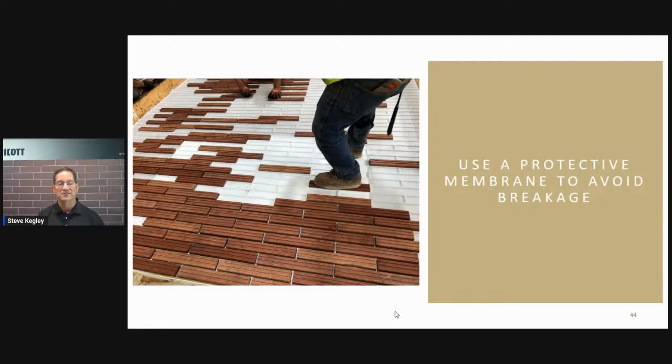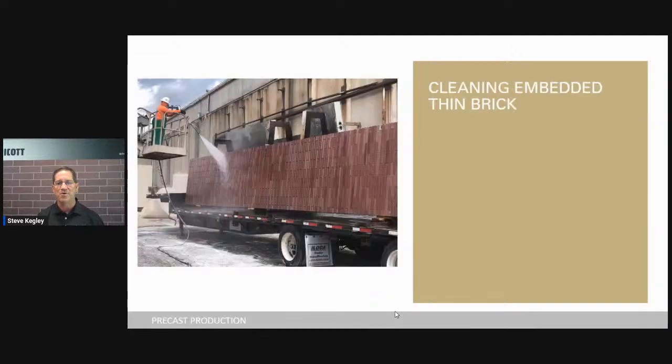Great practice to prevent that, because what's going to happen is he may slightly crack that, not know it, not see it, not take it out and replace it. Concrete gets poured in there. Now you've got to dig it out on the other side. After you clean it, you've got to dig it all out and epoxy a piece back in there and all that. All of you have had to do things like that from time to time. So that's a good best practice.